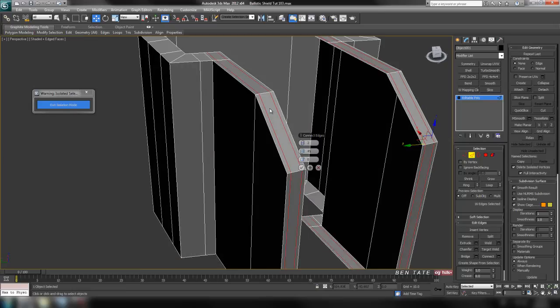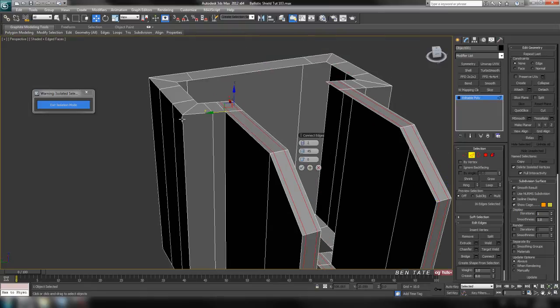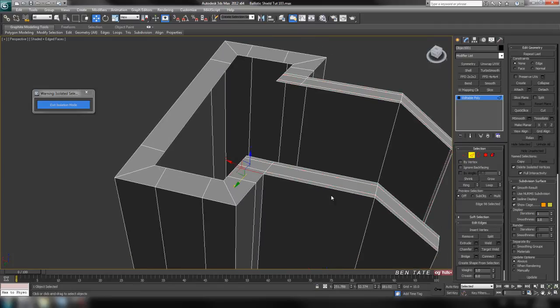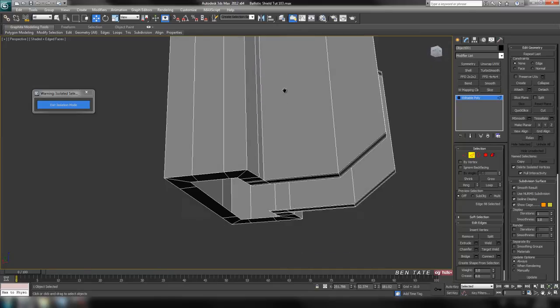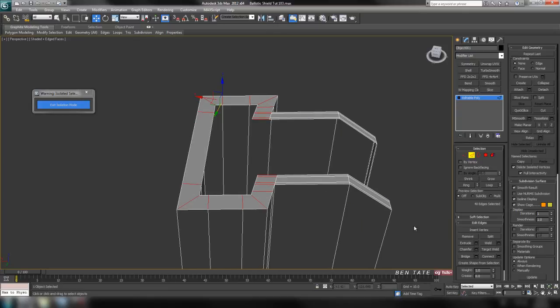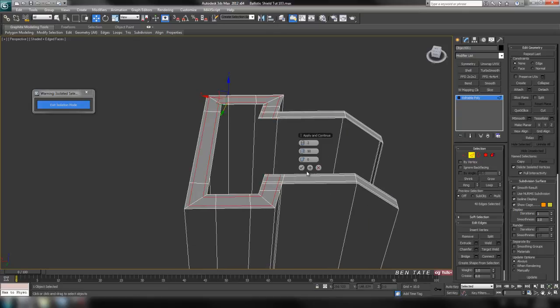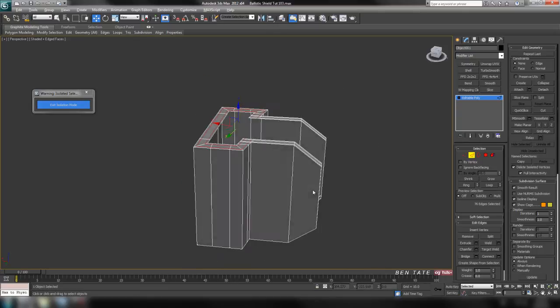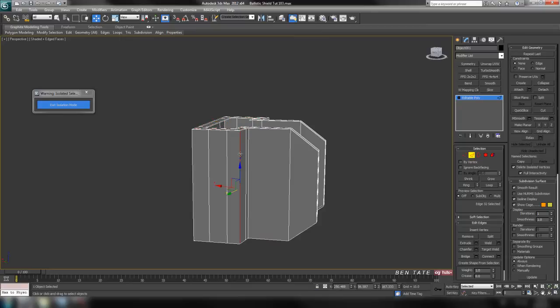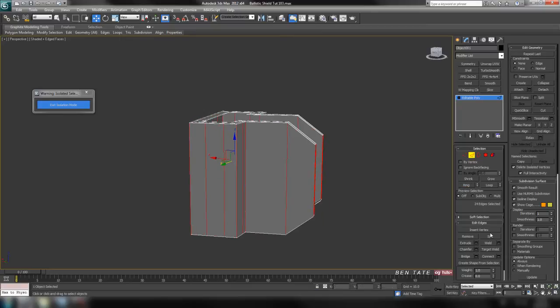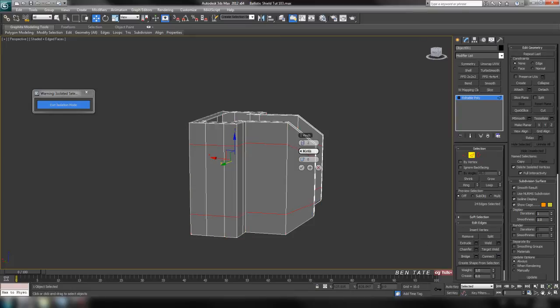And you want this piece to have quite sharp edges along the top, so we'll do about maybe 50 on the pinch. And okay. And same thing here. Let's ring that edge as well as the bottom one. Okay, and that should select all those edges there. Do another connect on it, and we'll just leave that at 50 with two segments, and okay. And we'll also do some at the top and bottom here on the sides. All right, so ring one of those side edges, connect it up, take the pinch up to say 95, and okay.